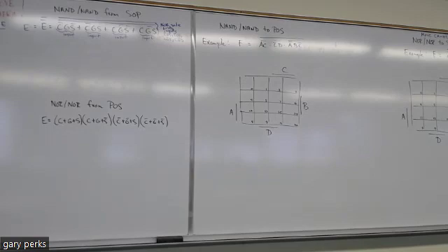Now, we talked earlier that De Morgan tells us that an AND gate is equal to an OR gate with inverted inputs, but that's only one part of De Morgan's, right? The other part of De Morgan's tells us that a NOR gate is equal to what? An AND gate with inverted inputs.